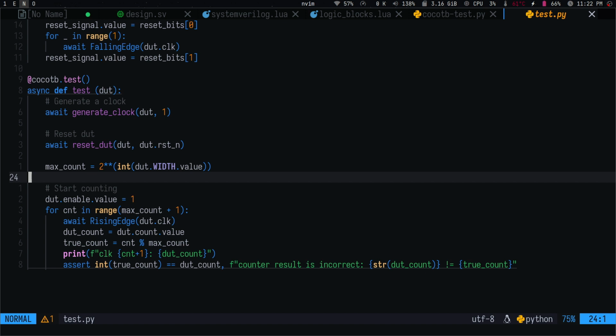Two is Python already comes with a huge amount of libraries. Let's say, for example, you are designing an FFT, a circuit that computes the FFT of some signal in hardware. Now you would like to test this circuit: if I give it this input, this is the actual output that I'm supposed to get. The question is, how do you generate golden input-output pairs? You say, of course, I will just write the code that takes an input and produces the FFT of that input.